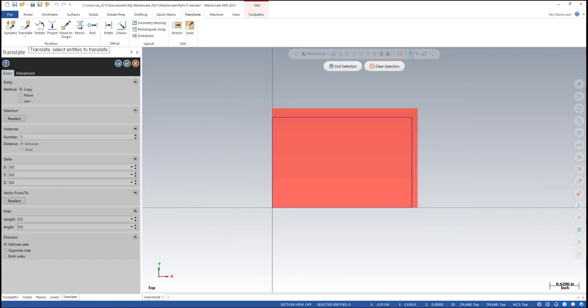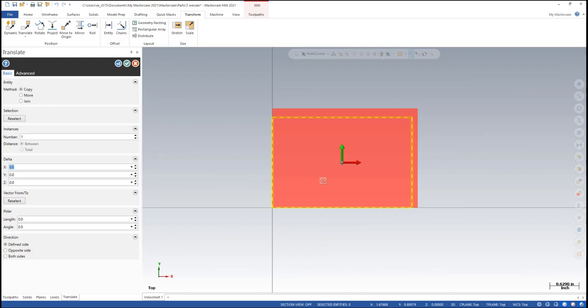You could also window select if you wanted to, however you want. But so we select all 4 sides of our rectangle in selection, and then we just need to apply our shift so we can do a little bit of math and determine what centered would be on our stock. Our stock was oversized 1/8 of an inch in X, so we need to shift it by 1/16 of an inch to have it balanced in the X side.